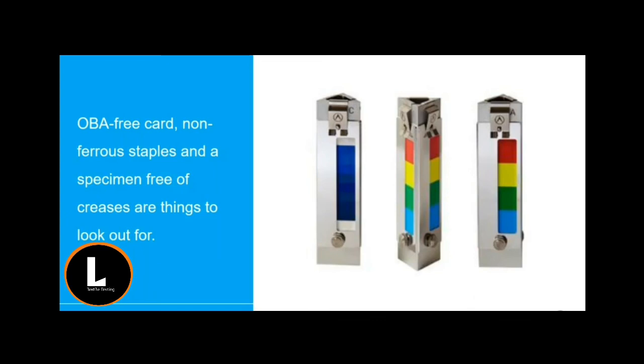The minimum specimen size is 45 by 10 millimeters. Specimens should be free from creases or any folds. You need to ensure that the masks or the covers are clean and flat. And a reminder of a previous slide, place any white card in any of the sample holders within the machine.